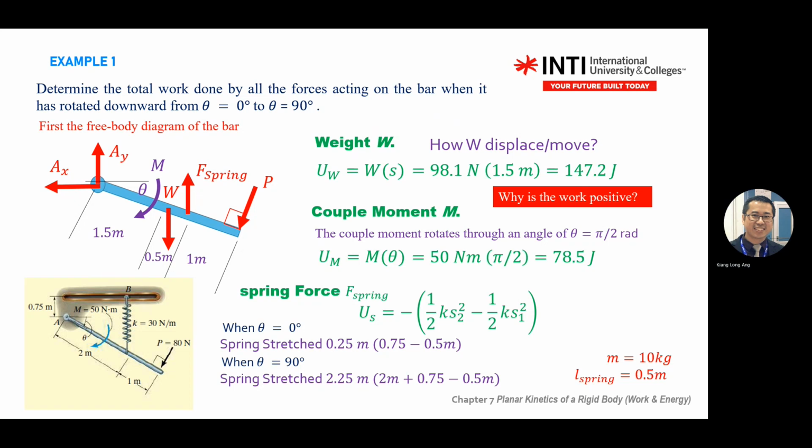The original spring length is what? 0.5. The gap here is 0.75. So at 0 degree, what is the length of the spring? 0.75. Can you imagine? So actually, before you start, you're already stretching your spring 0.25. Makes sense.